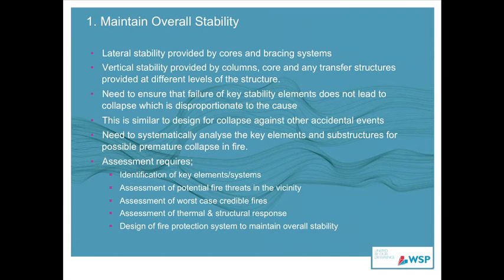So a proper assessment would require identification of the key elements and systems, assessment of potential fire threats in the vicinity, which is mainly based upon occupancy, assessment of worst-case credible fires, assessment of the thermal and structural response of the structure, and then design of the fire protection system to maintain overall stability for that particular building.